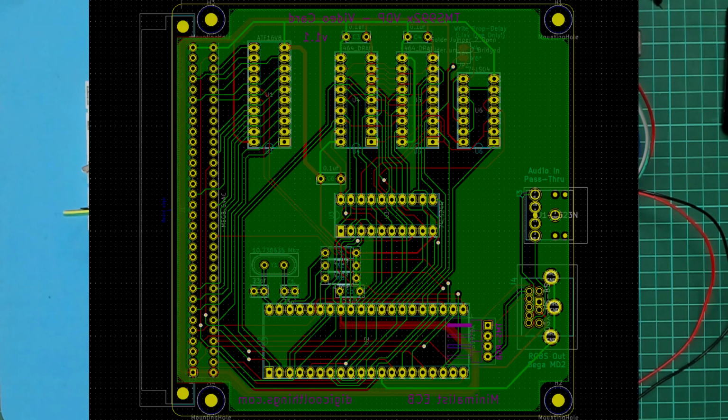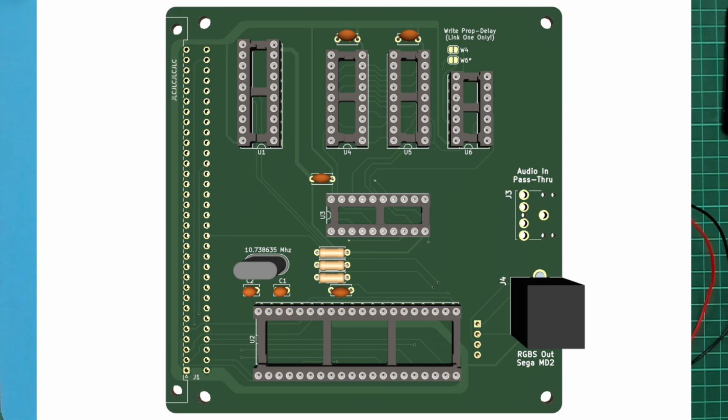As I've shown in the previous MECB videos, I created this KiCad project by using the standard MECB board KiCad template. This sped up the process significantly by letting me start off with a predefined PCB with mounting holes and with the bus connector and address decode PLD already in place and the PLD's traces already routed. As you can see, the rest of the PCB layout came together relatively nicely, with plenty of space available on the MECB standard 100mm square PCB size to allow for relatively easy trace routing on a simple and cheap 2-layer board.